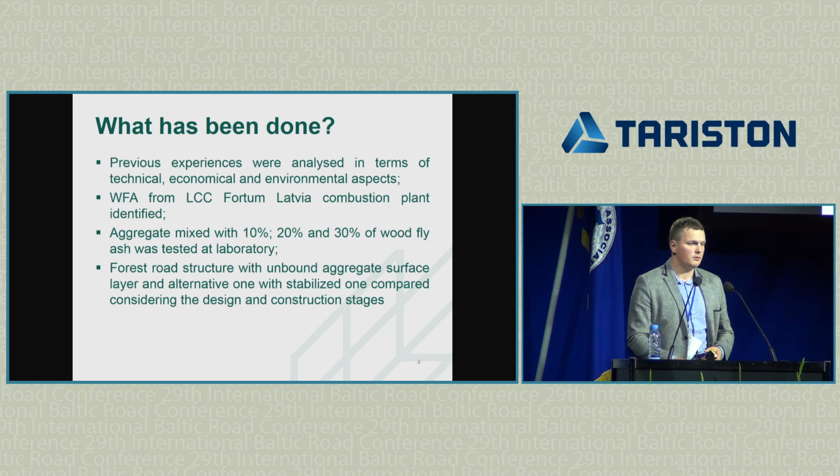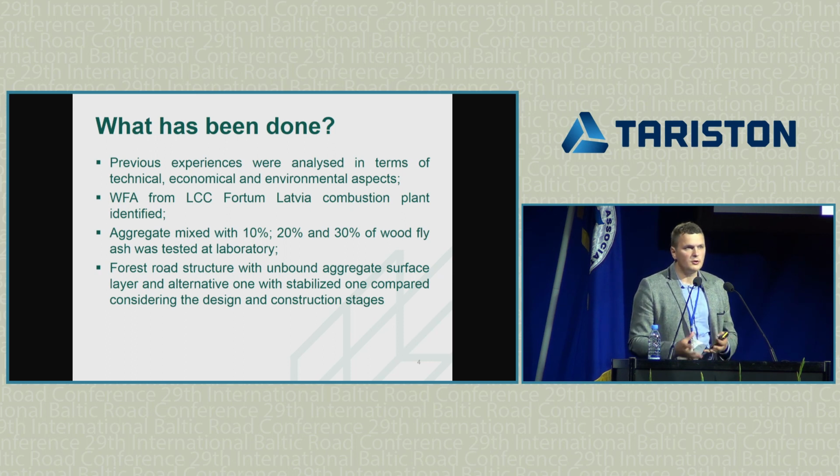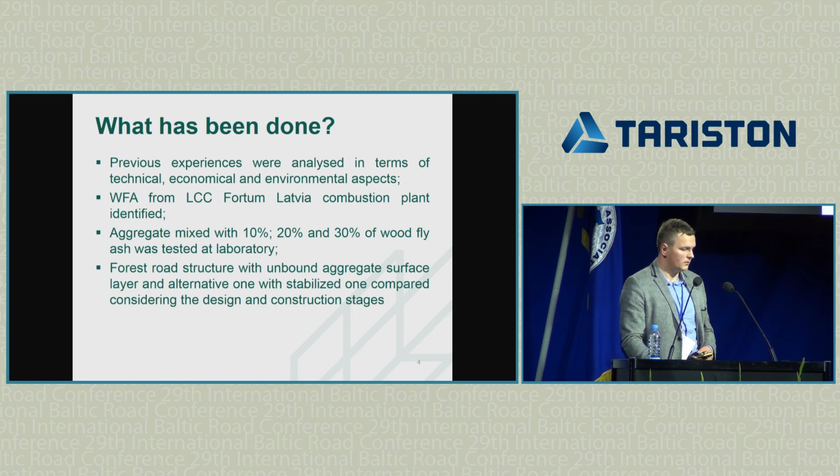If you talk about a forest road, it's the surface layer, and we used aggregate according to the existing specifications in Latvia for forest roads, and mixed them with 10, 20, and 30% of wood fly ash in the laboratory. We tested for the immediate response in the CBR test, the immediate CBR test, and then we tested also in an unconfined compression test after 7 and 28 days of hardening.